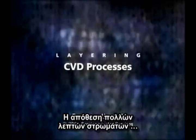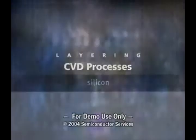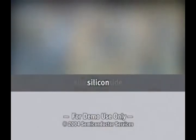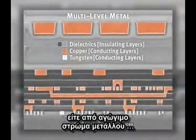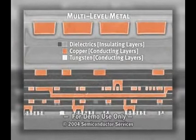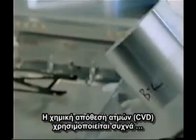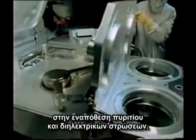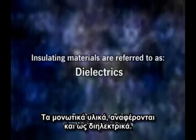The deposition of many thin layers is needed in building integrated circuit structures. A deposited layer may be a semiconducting layer, such as silicon, an insulating material such as silicon dioxide or silicon nitride, or a conducting layer of metal such as aluminum, copper, or tungsten. Chemical vapor deposition, or CVD, is often used to deposit silicon and dielectric layers. Insulating materials are referred to as dielectrics.